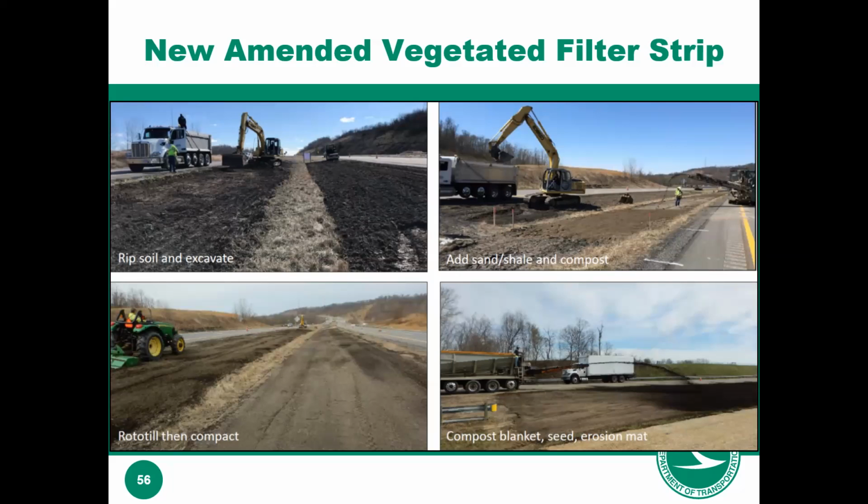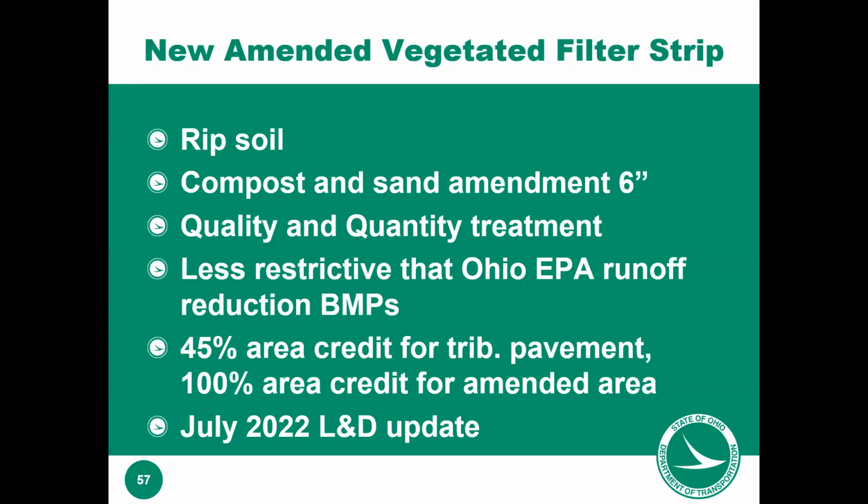And then we actually compact it a little, which seems silly for a BMP to compact, but you got to be safe next to the roadway. You can't have it being too loose. And then you put some seed and compost on it, and you get some treatment credit.